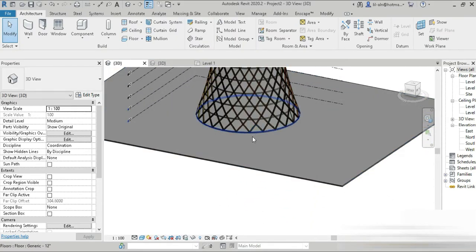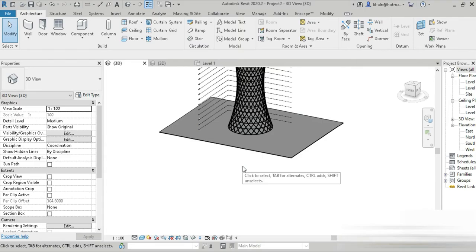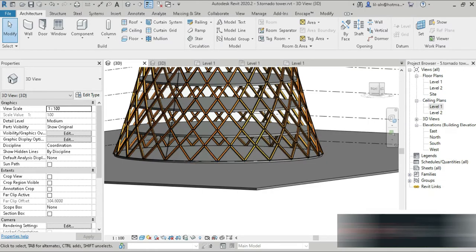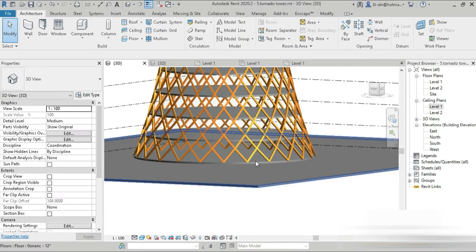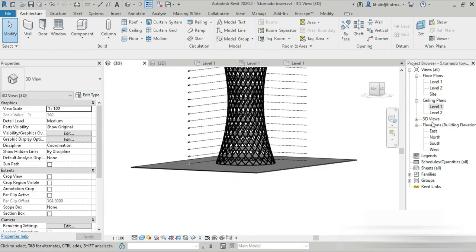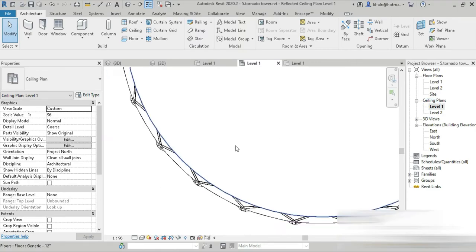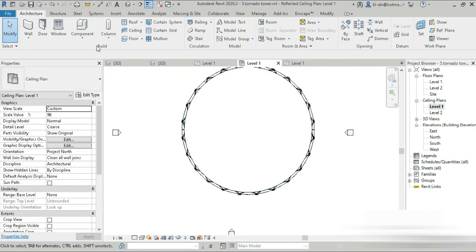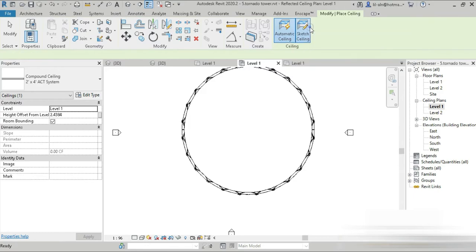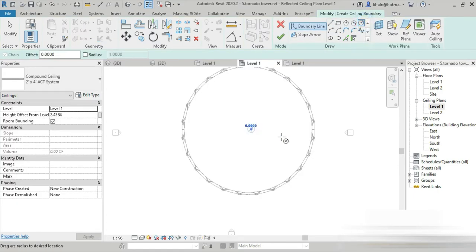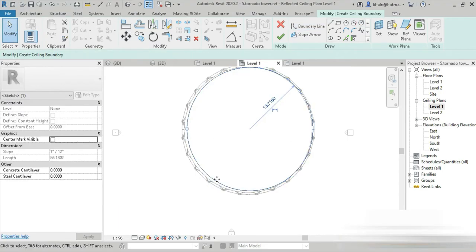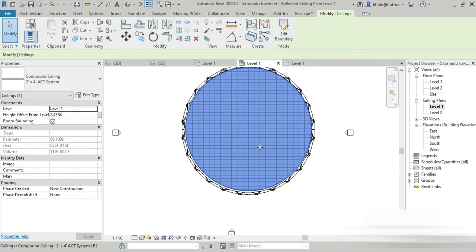Now they won't tell you that it's overlapping. So let's go and check out the rendered view of this, all right? And guys, before the rendered view, how about we make it slightly more exciting? Let's quickly go to ceiling plans and let's make a ceiling right here. So this is further going to improve our model. How about ceiling? Automatic is not going to work in this. How about we sketch, and how much? 45 feet. Okay, that looks okay.